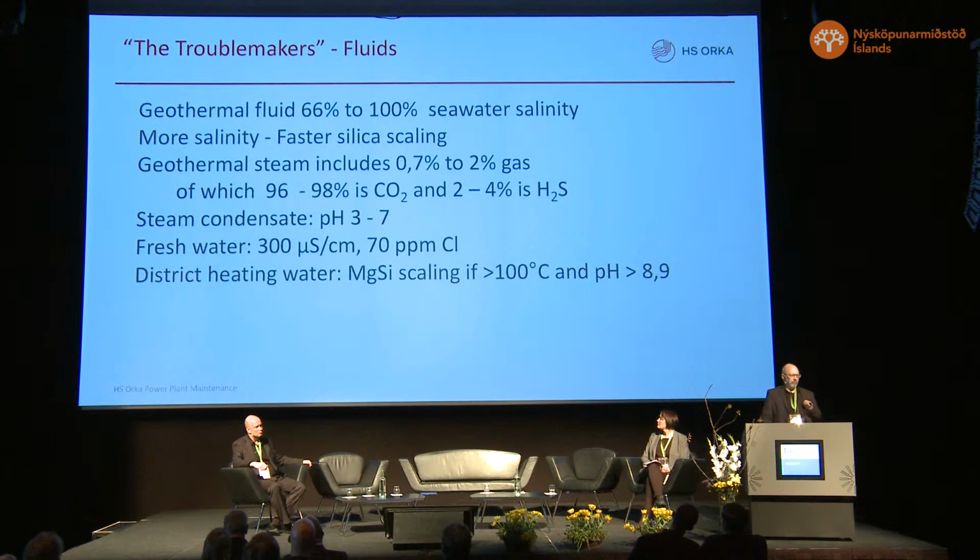The main troublemakers, so to speak, are the geothermal fluid. It is something we cannot control. Our geothermal fluids have a salinity of 66 to 100% of seawater. And what happens in salty water is that all chemical reactions are a lot faster, especially silica scaling.